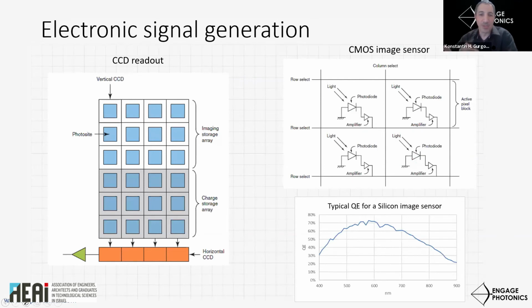So let's talk about image sensor noise. Photons are absorbed in the semiconductor, and the percentage of incident photons that is absorbed is wavelength dependent and is called quantum efficiency, or QE. Upon absorption, an electron-hole pair is generated, and the charge is accumulated and stored in the pixel until readout. The image sensor accumulates the signal charge during the exposure time that is set in the image sensor.